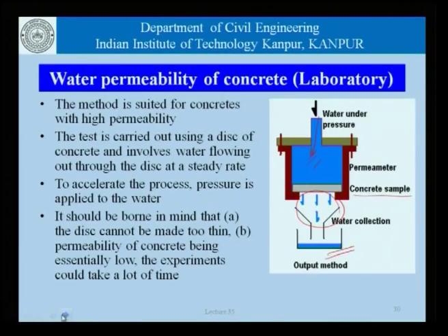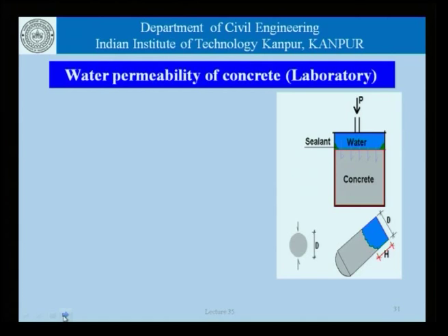So, the pressure applied has to be limited from that consideration, and it should be borne in mind that the disc cannot be made too thin. The permeability of concrete being essentially low, the experiments could take a fairly long time. To address this, we often carry out the test using the depth of penetration method.